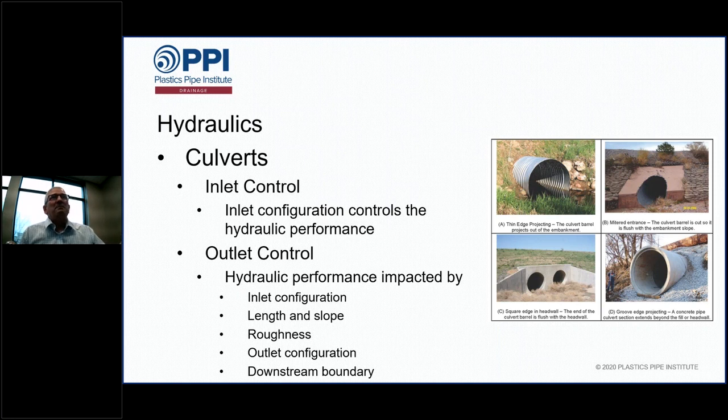It's because the inlet is shaped in such a way that water can't get into it quickly enough to completely overwhelm the pipe below it. That's about the easiest way I can say what inlet control is. Basically the inlet section controls the design.